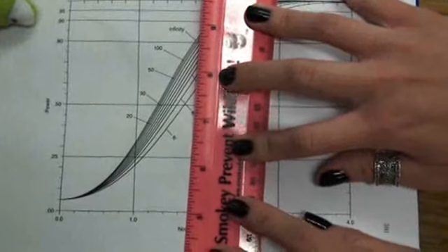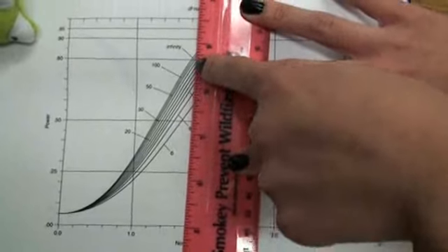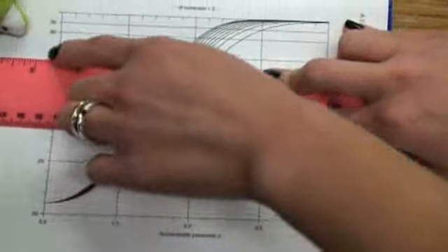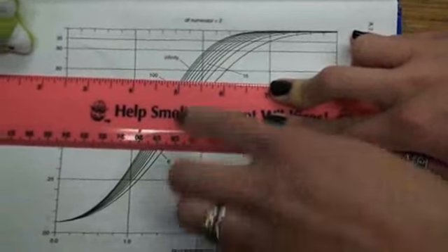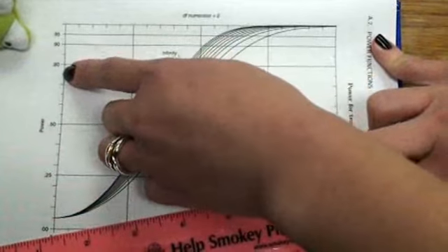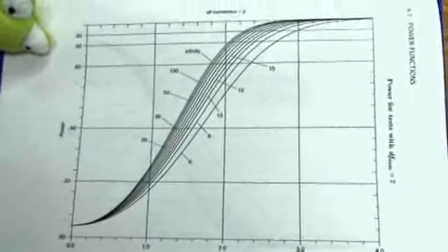When you move it up, you're going to look for, by conventional standards, where it crosses the 50 power line, which is the 3rd line. Where it crosses that, you're going to move over, and this right here will tell you how much power you have. So our phi of 1.78 crosses the 50 power line around somewhere just underneath 0.8 power. We use the 50 line because it's the accepted standard convention.